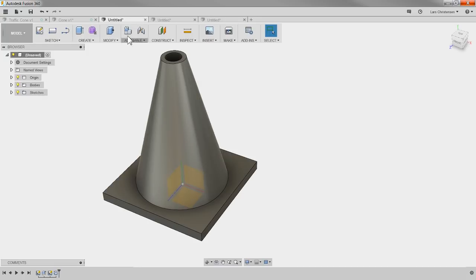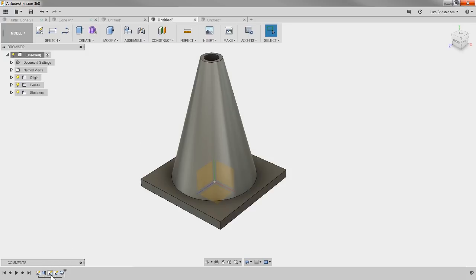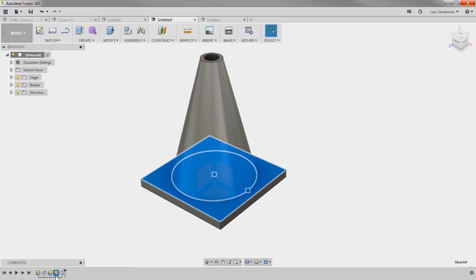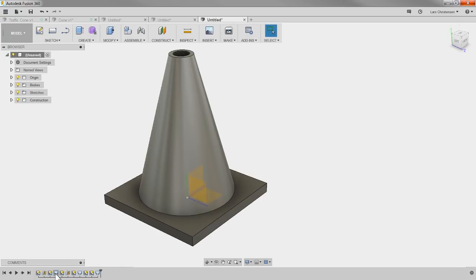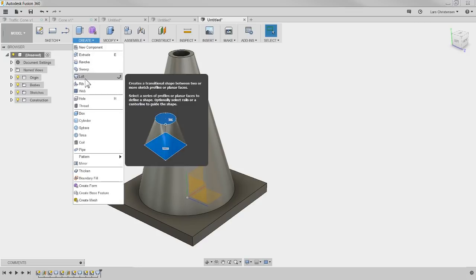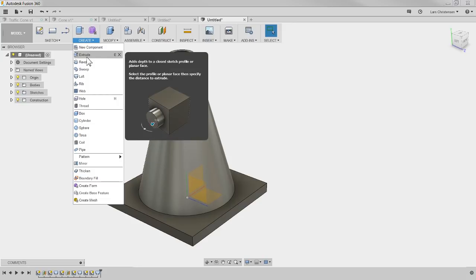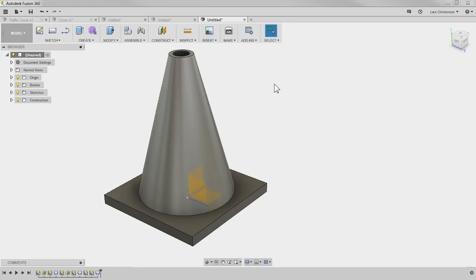Now be aware that you can make good round things with the Revolve command. I hope you saw that. You have the sweep command that uses 2 sketches, a profile and a path. You can also use that for round. And then in the end, you have this loft command that lofts between different profiles. So my hope tonight was to show you some of the different ways you can work with these tools. Brand new, just stay with the extrude for now, but be aware of the other tools and what they do. All right, let's see here.